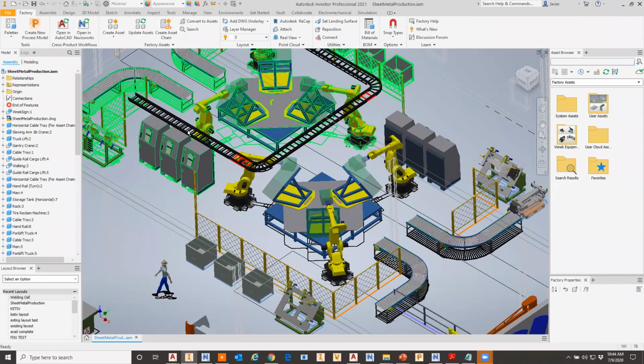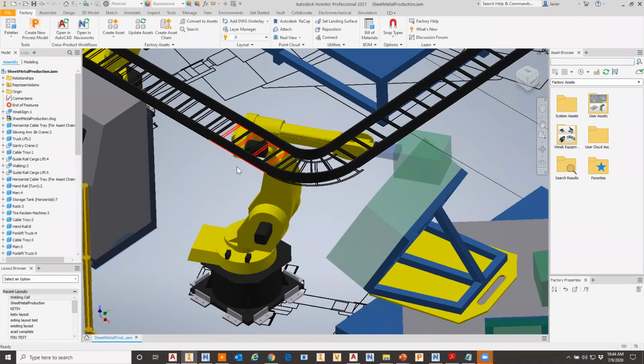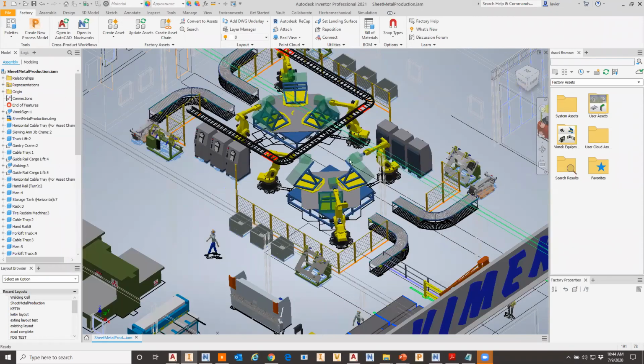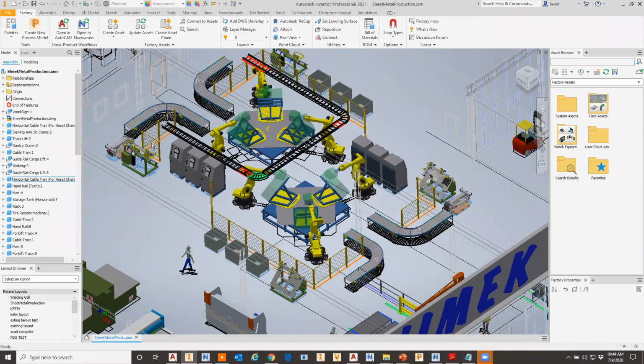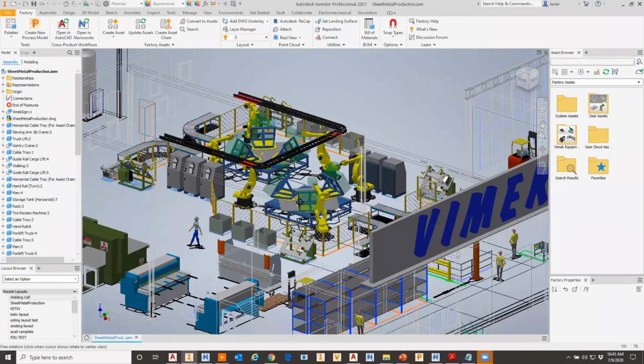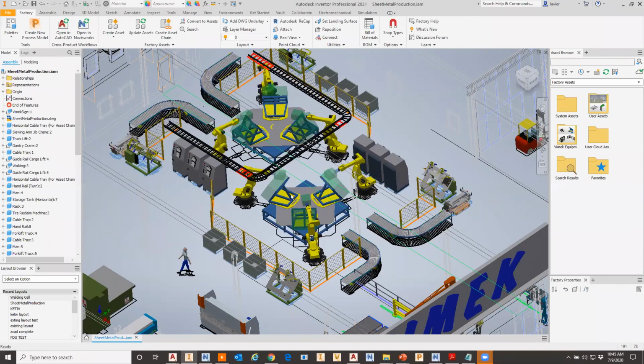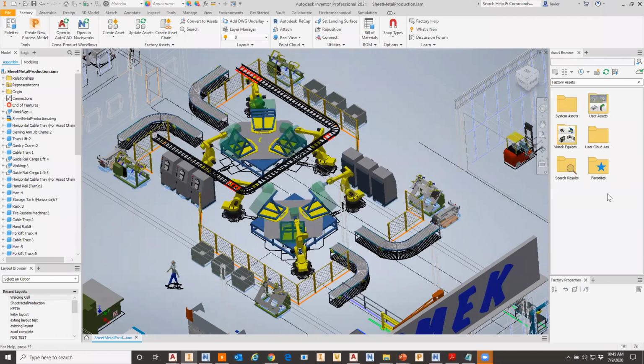Some of the other machinery, if you notice a cable tray here, I drew as a polyline, and it drew a standard segment, and then right here there's a non-standard segment, and it highlights it in red. That lets me know that might be a custom cable tray segment that I might pay extra for. So when I have situations like that, we'll be able to see that. And it is elevated; you can see it's elevated above the facility there. So we could continue the process. There's more stuff we need to add.